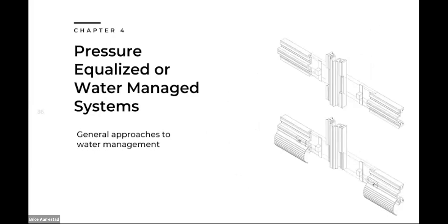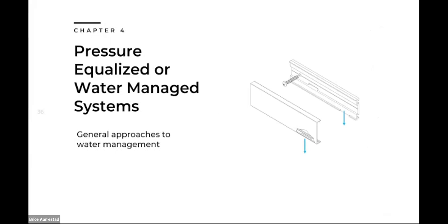Here you're seeing just a quick diagrammatic of the gasket system and how gaskets are sealed to allow that air barrier to be continuous on the interior side of the glazing assembly. We also use ventilation slots. These are small vents or weep holes that are placed in the mullion caps and also routed through parts of the pressure profile that allow the interior cavity to allow air to flow freely. And they help match the cavity pressure to the exterior pressure.